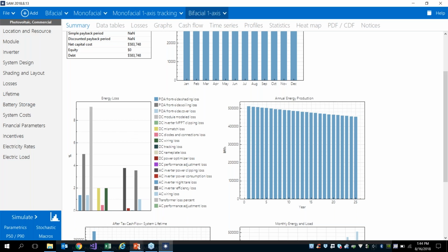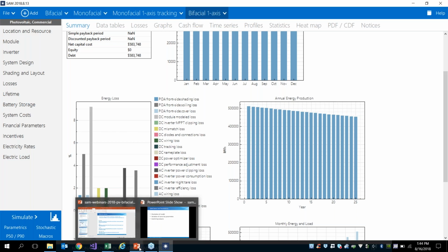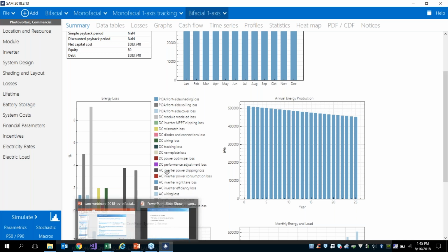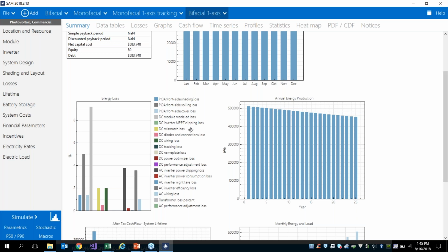The underlying model that we've used for the bifacial irradiance model, since it's only calculating the irradiance on the rear side, does not get into any mismatch issues, and we have not considered them at a first pass here. We certainly do acknowledge that they should be accounted for at some point, but we have not yet done so. I'm not 100% sure, but I think there are some proposals and work going forward over the next few years to investigate what that effect looks like and how to model it, but we don't currently have the model for it.